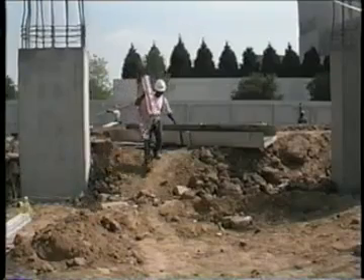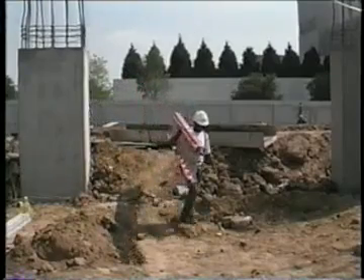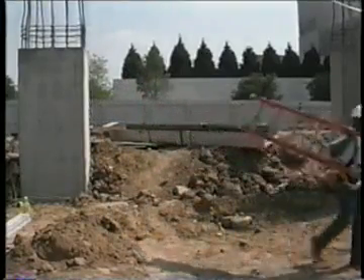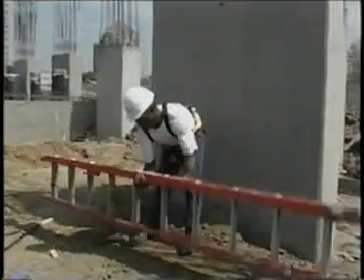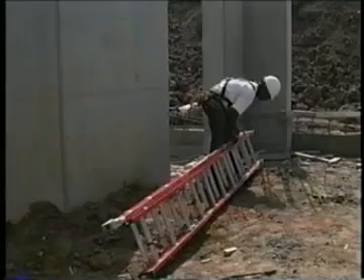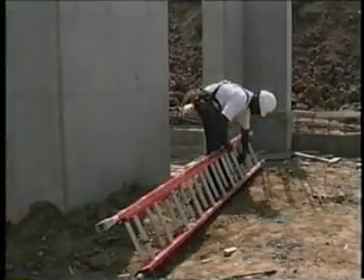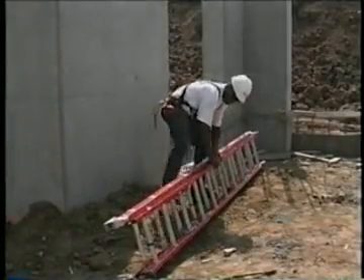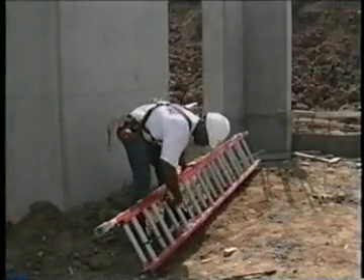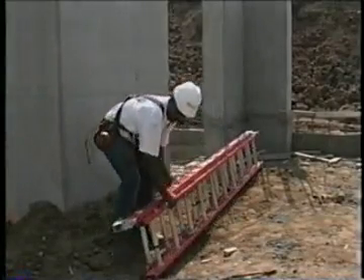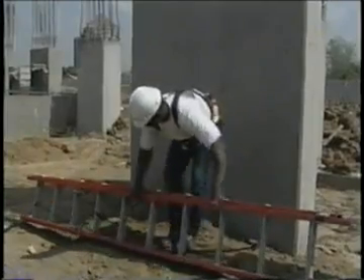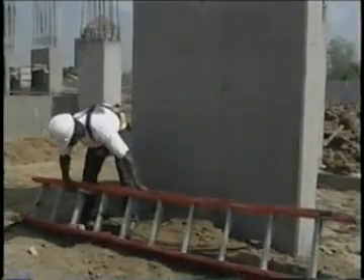Falls from ladders are the 3rd most common cause of falls that result in disabling or fatal injuries. Most of the falls in this category occur at heights above 10 feet. Inspect each ladder before you use it. The ladder must be taken out of service if it has cracks, dents, or bends, broken rungs, or defective steps. Check the design strength of the ladder to be sure it will hold the amount of weight you'll be putting on it.